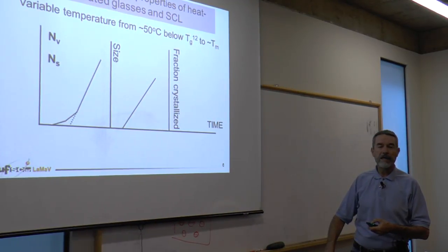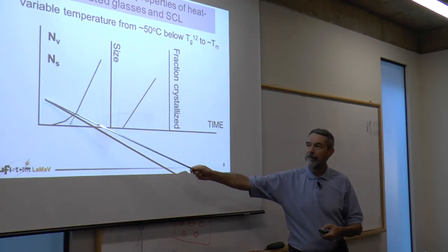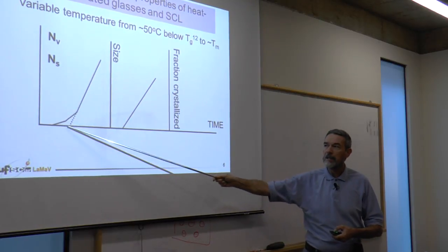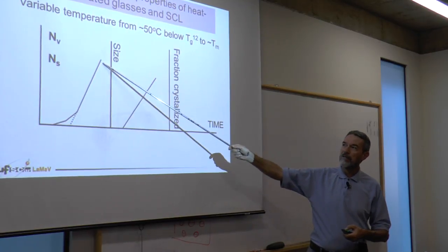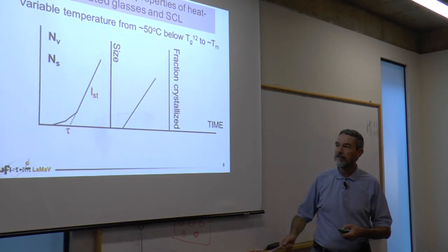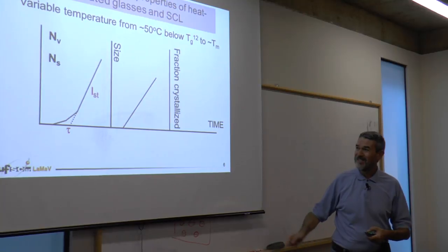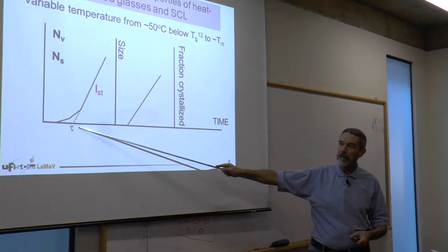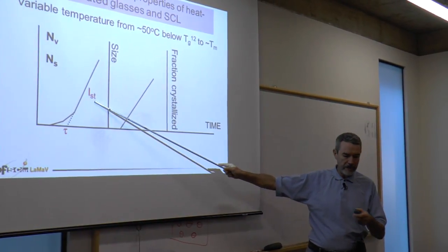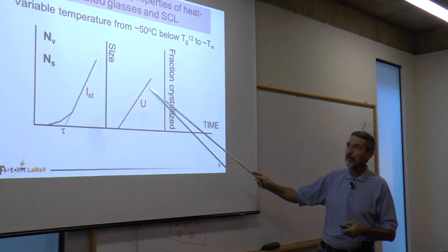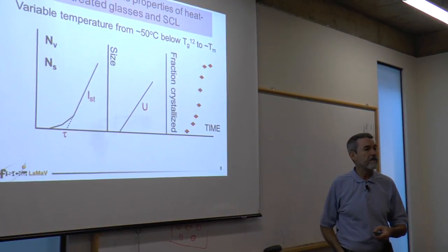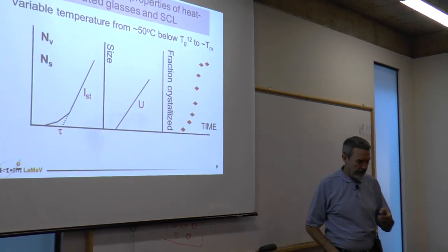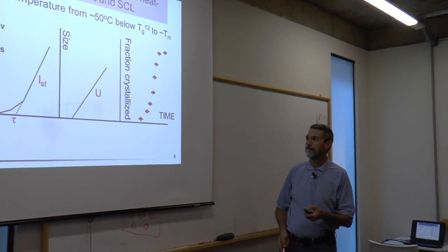We also have seen that we normally measure the number of crystals versus time to get the nucleation curve, and from the nucleation curve, two kinetic parameters which are temperature dependent can be obtained: the induction times and the steady state nucleation rates. We can also measure growth rates and the overall crystallized fraction, but these two phenomena will be dealt with in the next few weeks.